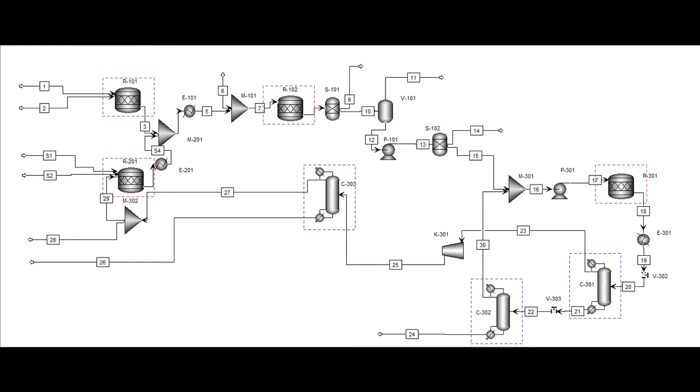As for the specification of the three distillation columns, a DSTWU model was used for all three distillation columns due to this being the only model in the columns section in Aspen to only require the specification of the condenser and reboiler pressures and separates in accordance with the boiling points of the components being separated, so the heavy and light keys. Now, for the description of the process, each unit will be assessed starting from the DC reactor and ending with the OC reactor.